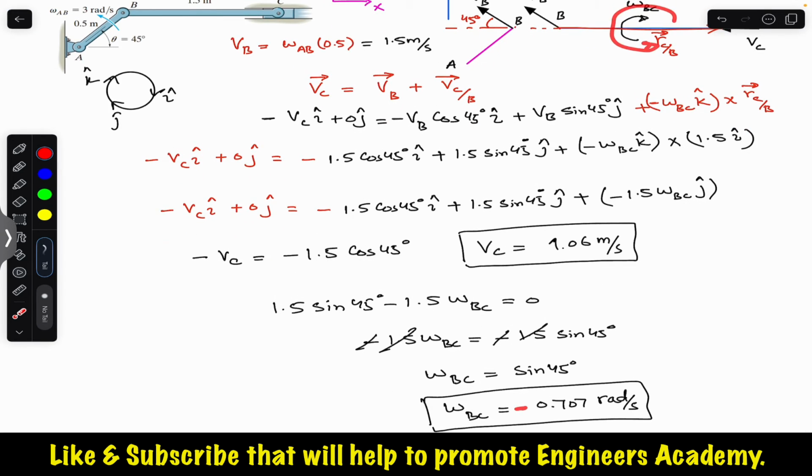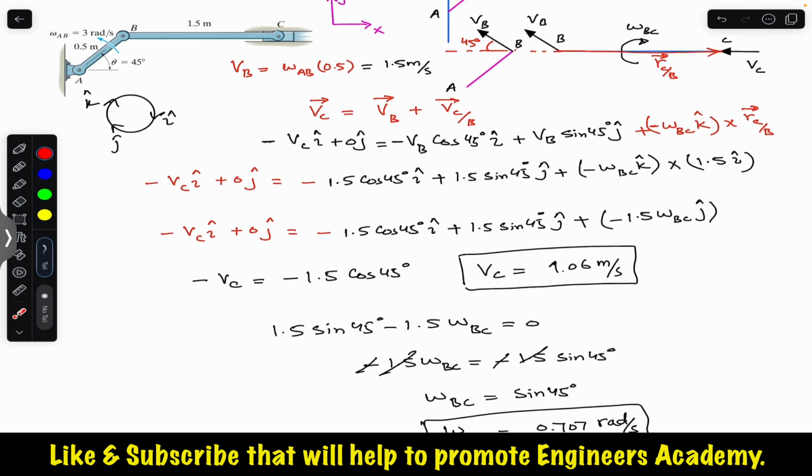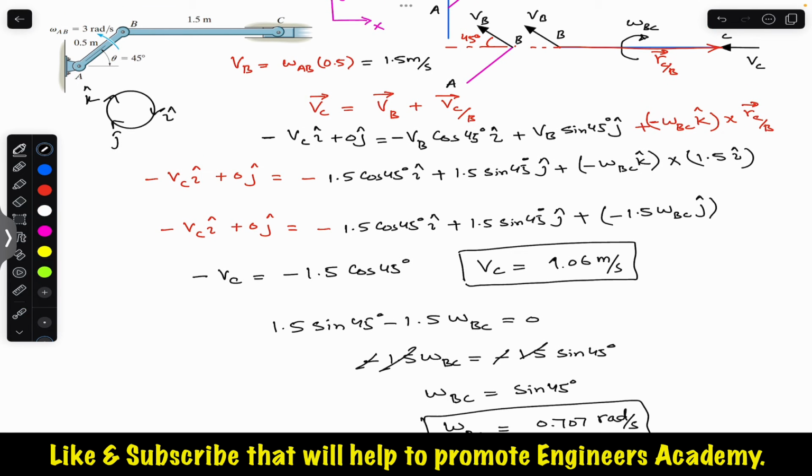Now the answer is positive, so the assumed direction of omega BC is right as well. So omega BC is in the clockwise direction. Magnitude is 0.707 and VC is towards the left of magnitude 1.06 meter per second.